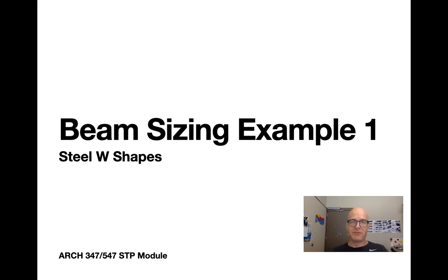Later on, in a different video, we'll do one in timber and show how we back the section modulus figure that we need out of some simple formulas to calculate S. In this one, I want to just go through a simply supported distributed load on a steel beam. This is by far the most common and one of the simplest ones. It's one where we can use some formulas and have some shortcuts. So we'll get to some answers relatively quickly.